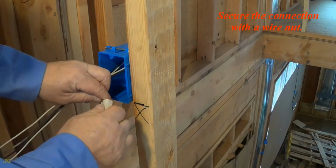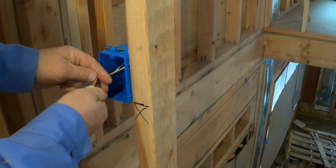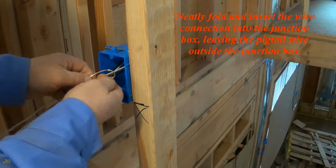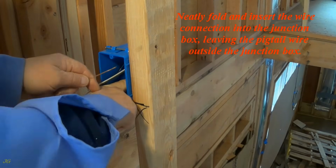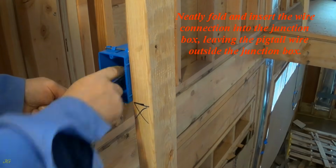Secure the connection with a wire nut. Neatly fold and insert the wire connection into the junction box, leaving the pigtail wire outside the junction box.